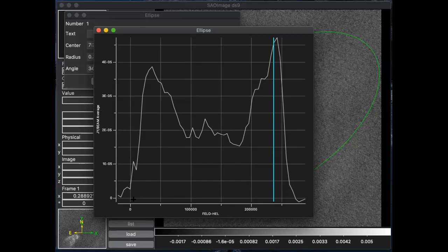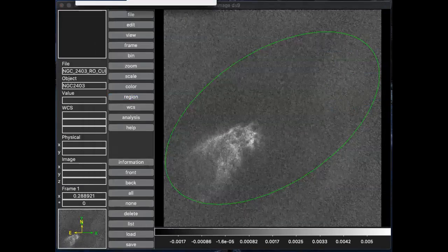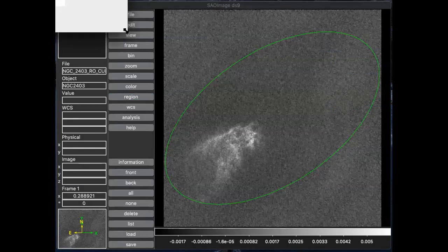As you see, this has what is known as a double hump structure or double horn structure. So this is one horn, this is the other horn. This is approximately the center of the frequency channels. Now it turns out the distance between these two horns is given by this formula. The distance between these two horns is essentially 2v0 sine i.